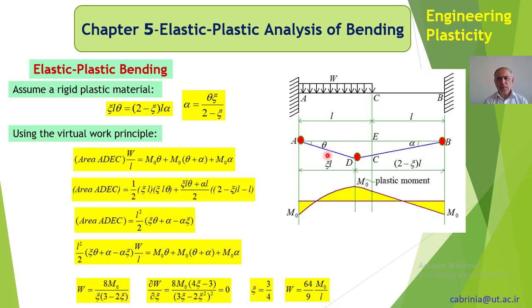So minimizing or maximizing, putting it equal to 0, we could find out the position of this collapse load as well. But in other more complicated problems, you don't know where the hinge is and you have to guess and then solve the problem, and maybe you have to have many guesses and solve the problem for all the options and then see which one is correct. I will get to that in a few slides.